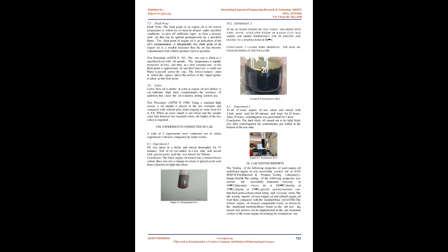Density is the ratio of the mass of a volume of oil to the mass of the same volume of water and depends on two temperatures, at which the mass of the oil and the water are measured. Density is influenced by the chemical composition of the oil. An increase in the amount of aromatic compounds in the oil results in an increase in the density, while an increase in the saturated compounds results in a decrease in the density. Density is an important quality indicator for automotive oils where it affects pricing, storage, handling and combustion.